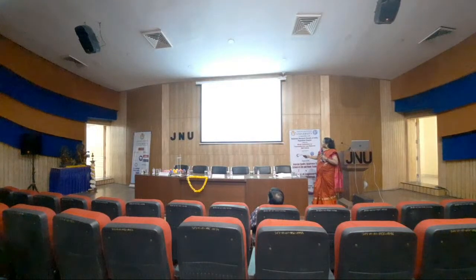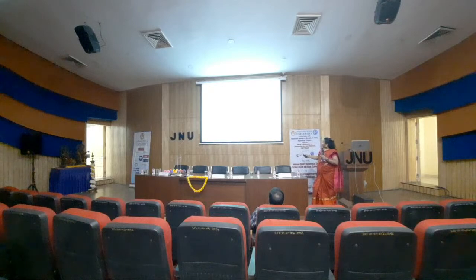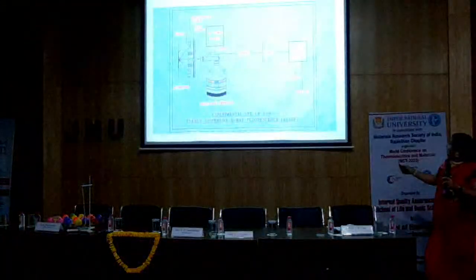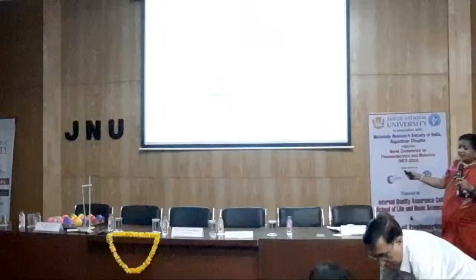We had assembled this in BRC. You have the radioisotope source, which is a ring source. It strikes the sample here. The backscattered, reflected X-rays fall on the beryllium window of the detector. The detector is only this much. What is left is the dewar, which carries the liquid nitrogen to cool it, for several reasons, to discard the noise and all that. And here you apply a high voltage of around minus 800 volts, which is again amplified and shown in a multi-channel analyzer, which is PC based, and you have the data.